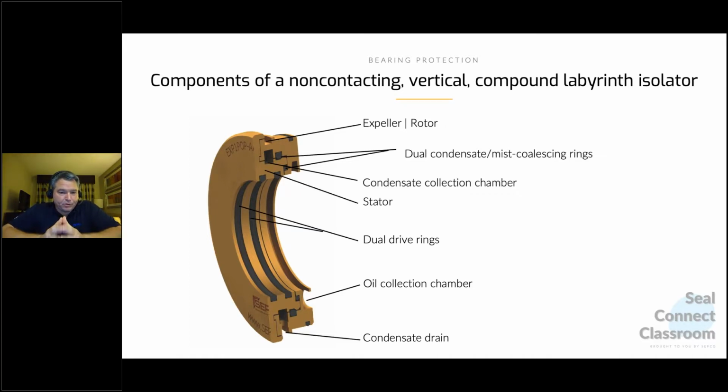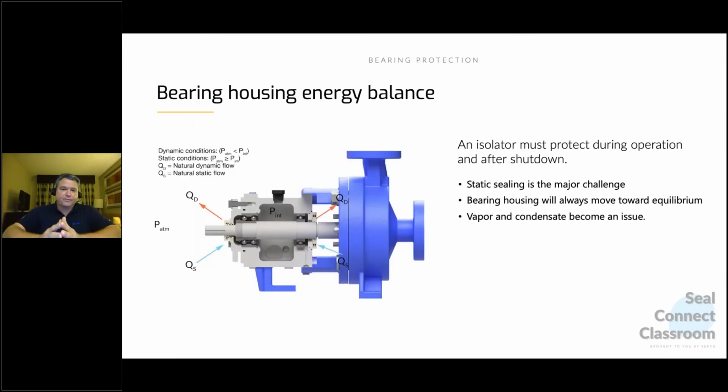Breathers are important. Number one, have a good breather, a desiccant breather, a good filter breather, to help prevent contaminants getting in through the breather. Let the machine breathe good, clean air. When it's venting out, when it's running, that's great. That's where those hook vents come from.